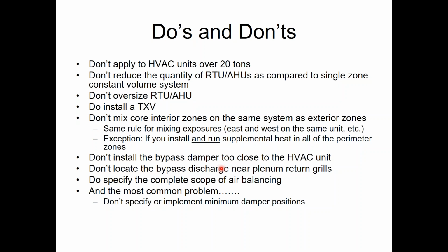If you do that, you're going to end up with the problem jobs, the whole interior and perimeter mixing and all of that stuff. Definitely do not oversize the equipment. It's worse than in any other scenario. VVT is the worst thing to have oversized air handlers on. Everybody's got a TXV now, so that's easy.